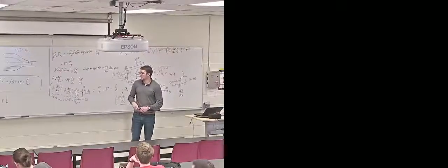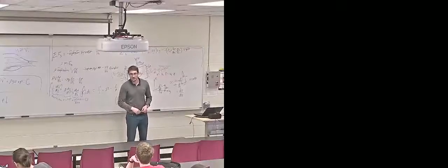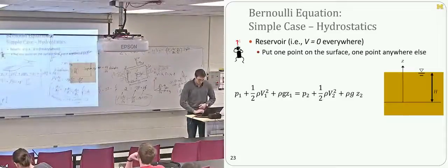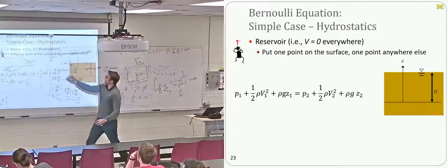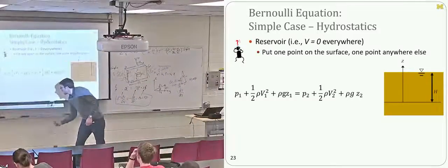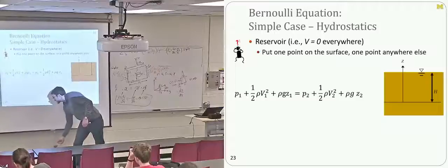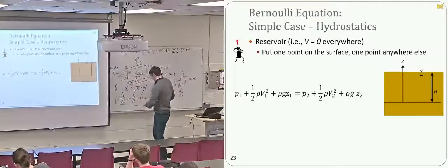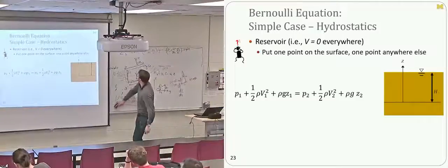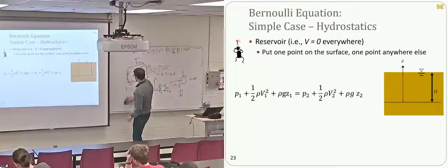This is the equation behind, as I said, showing why wings work, right? The flow over the top of the wing is faster, pressure decreases according to the Bernoulli equation, creates suction. Sucks planes up into the sky. So now let's look at a. I'm going to go ahead and erase this.